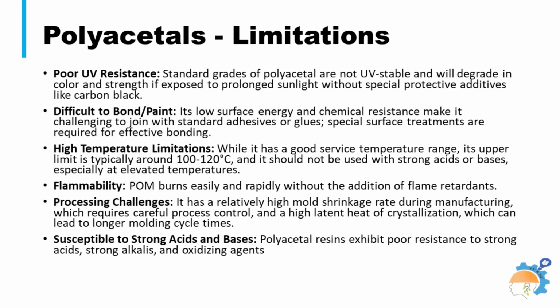Without special UV stabilizer additives, polyacetal degrades quickly with prolonged sunlight exposure. It has low resistance to strong acids, e.g. sulfuric acid, and alkalis, limiting its use in these specific chemical environments. Their low surface energy and high chemical resistance make it very difficult to glue or bond effectively without special surface treatments, requiring mechanical joining methods instead.